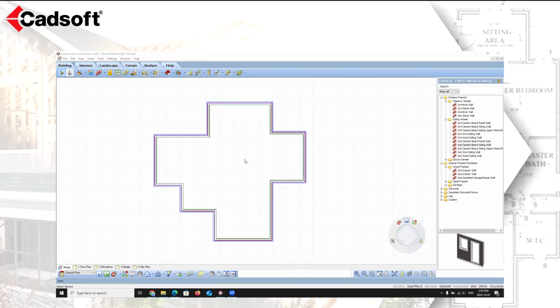When you use the Roof by Perimeter tool, the program detects your model's perimeter walls and it will automatically place a roof over top of them. To be able to use the tool, you need to have exterior walls in place in your design. And they must be in a formed closed layout. So every wall must be attached at a corner.